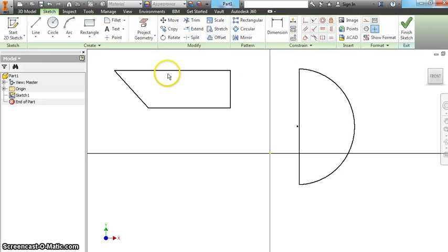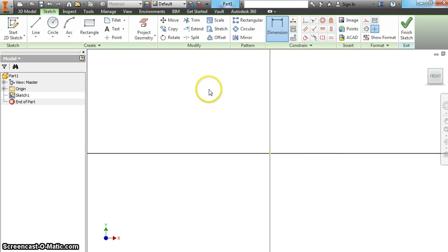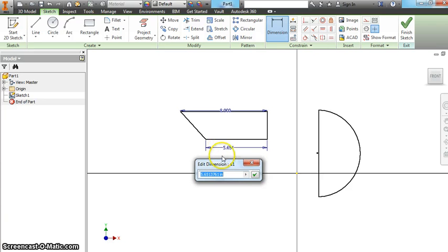The cool thing with Inventor, you know you're going to measure. It has to be specific measurement so it doesn't hit the bottom of the stand we're using to hold up your tower. So let's say I want this line to be, okay, that's really small, 0.774. Let's say I want it to be 8 inches. Okay, it jumps off the screen, don't be alarmed. Click front, it will resume that. If that's 8 inches, this obviously has to be less, and it's automatically resized it for you.